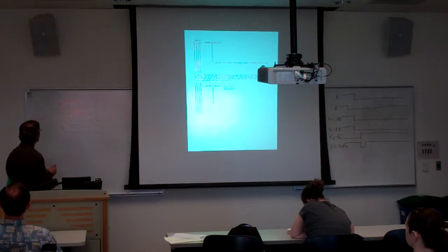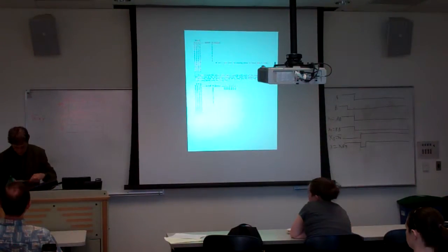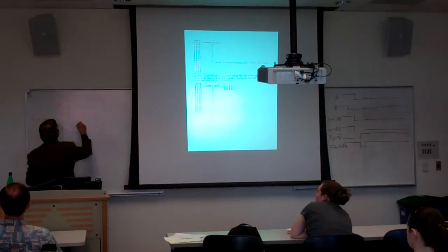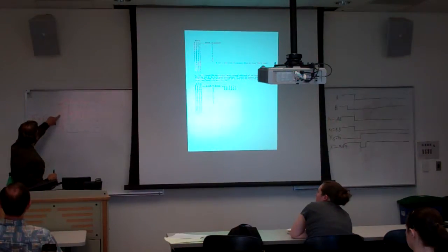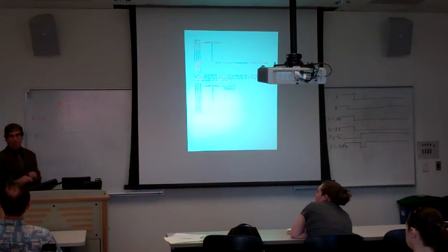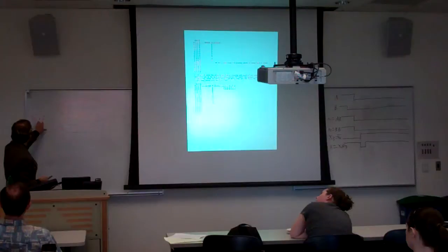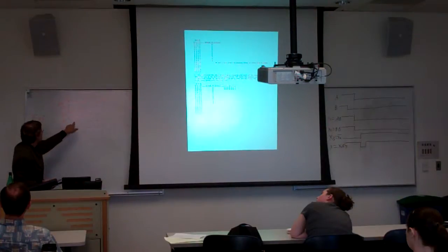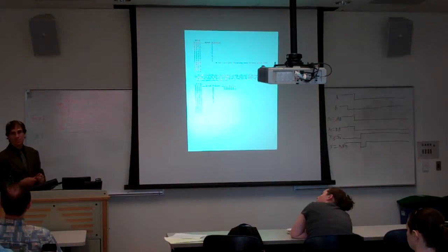Now if we covered 4 of these, W can have either 0 or 1, and we're still inside this rectangle, so we don't need the W term anymore. All we need is X to be equal to 1, and for Y to be equal to 0. That's a smaller expression. We've used the fact that if X is 1 and Y is 0, we don't care if W is a 0 or a 1. If it's a 1, it just puts us into these cases where we didn't care what the output was. So we can ignore that term. So we have a simpler representation.